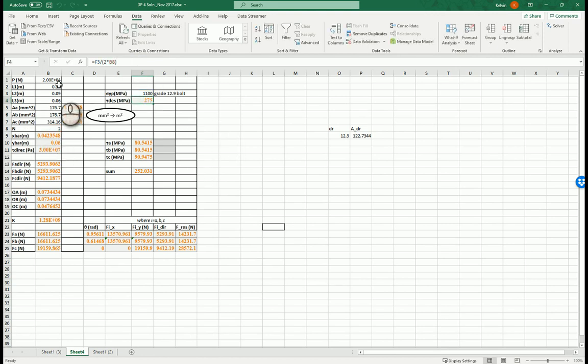Right, so go ahead and try and get your equations. So, for example, X bar, again, is taken from your notes. So you notice I use the areas in meters. Y bar, tau direct. Right, so the force divided by the sum of the areas. Right, so use the example 2 equations and complete your Excel sheet. And you can pause the video at this point, and when you're finished, you can ensure that your Excel sheet is working and you're getting your values for shear stress as indicated here. Right, then we will move on to the optimization part.